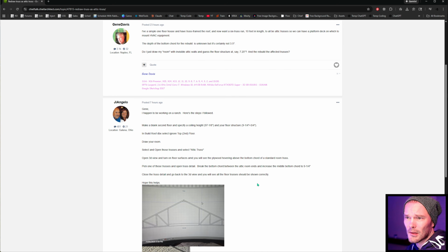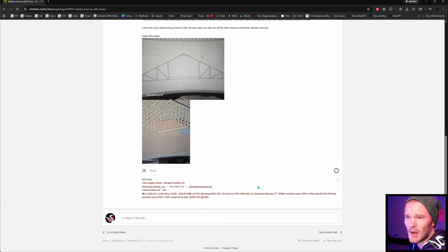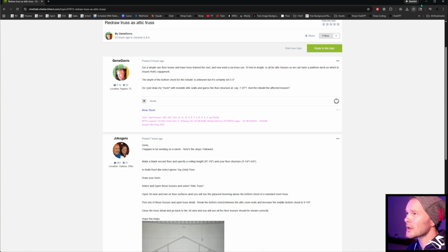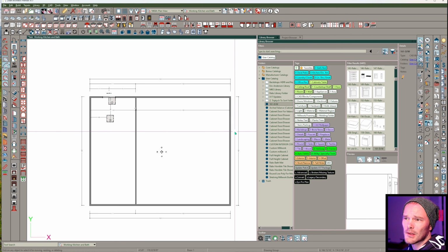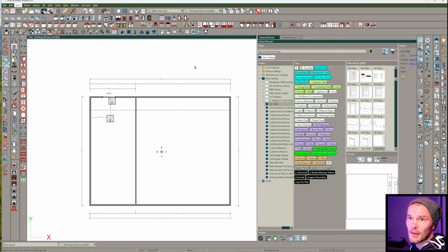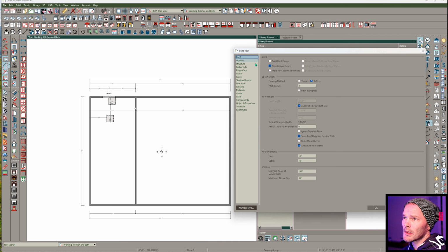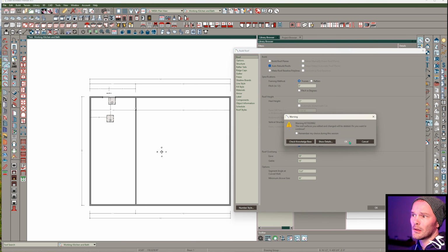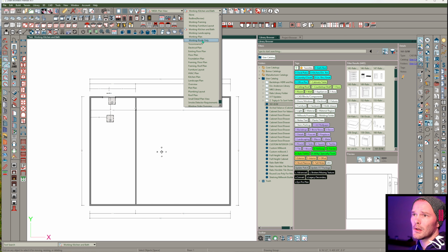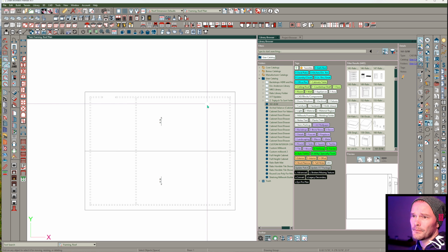I'm having trouble understanding that question, and so I'm not quite sure. Let me see what an answer is. I'm not quite sure what they're getting at for that. But let me just go ahead and make it be conducive to just simple attic trusses here. And I'll get to my auto build roof. And let's make these trusses. I don't need to see them on this display. We'll show them on a framing view.